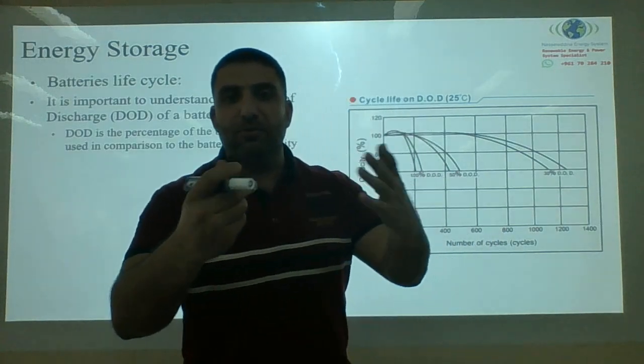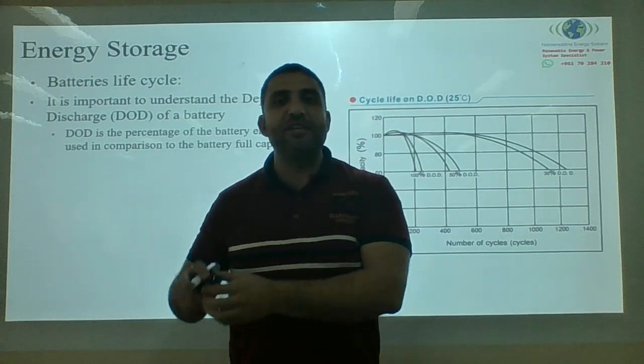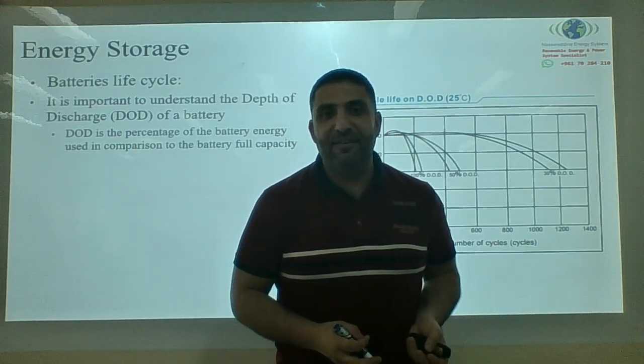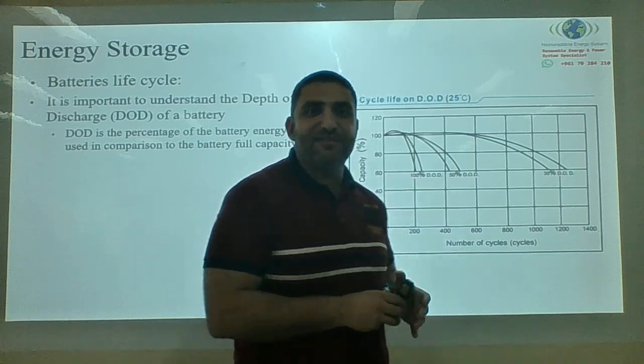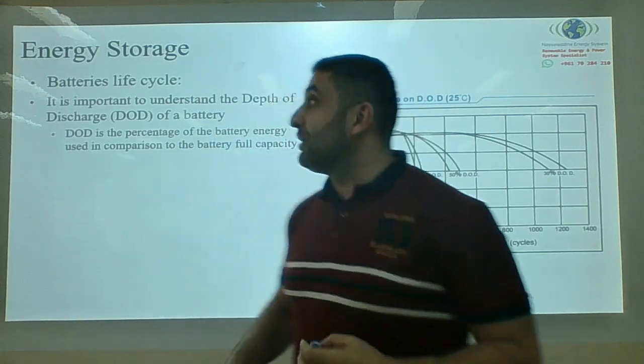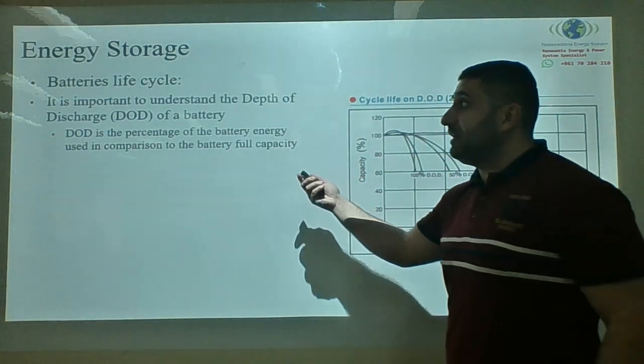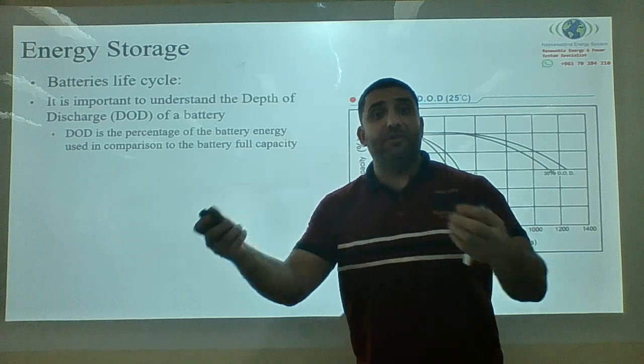Hold on a second. No, you don't. Your battery size is this, but you can only use 7 or 8 kilowatt hour. That's why it's very important to know the DOD, the depth of discharge, because it will explain how much you can take out of it.